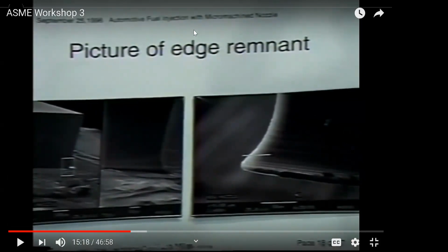Okay, so I think we almost run out of time for today's lecture. So again, you see the design of MEMS and fabrication of MEMS, this kind of sensor, is still an important thing, right? You see, for this particular MEMS pressure sensor, the packaging is also an important thing. Again, mechanical stress is also important for this packaging issue. That's why, as I mentioned before, it's still challenging for all you engineers to come up with a good design of MEMS sensor, good fabrication and packaging, right?